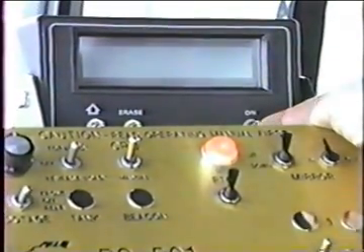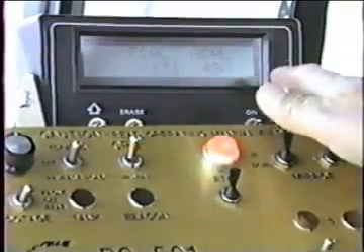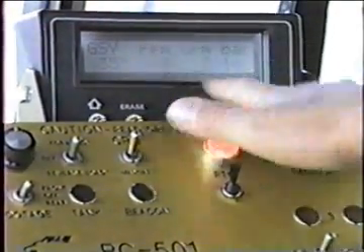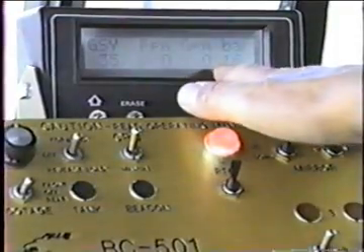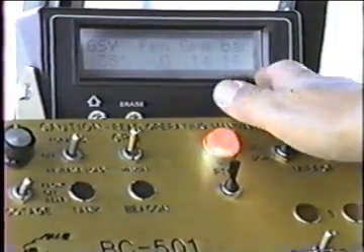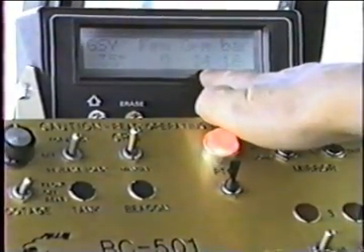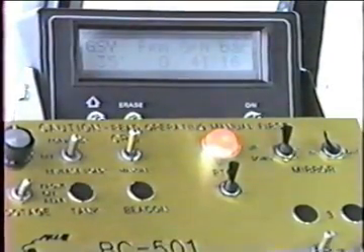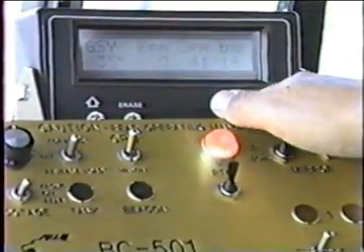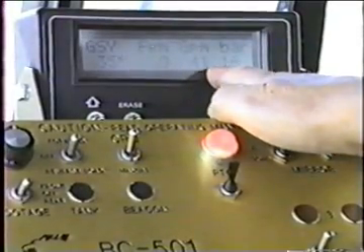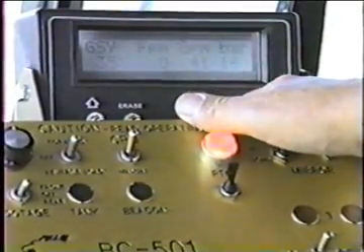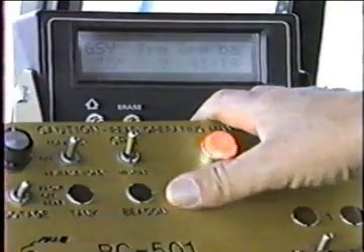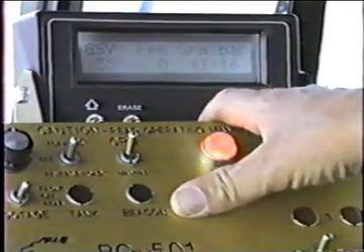Turn the computer on. When it comes on, you'll see Bearcat, you'll see some calibrate numbers come up. Now it says GSY, FPM, GPM, and spray bar. Now the pump has started to turn. Because the master switch is turned off, the computer is in the idle mode, and it'll circulate the asphalt pump at whatever gallons per minute we have in the memory for the idle mode.